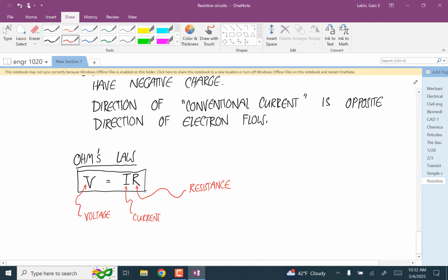If you solve for the current, and let's say voltage is equal to 10 volts and resistance is 100 ohms, then the current is going to be 10 over 100, so 0.1 amps. If you want to increase that current for the same voltage, then you can reduce the resistance, make the energy flow more easily. Let's say the resistance then is 1 ohm, and now you have 10 amps of current flowing through. So intuitively it makes sense, but this is the mathematical relationship.